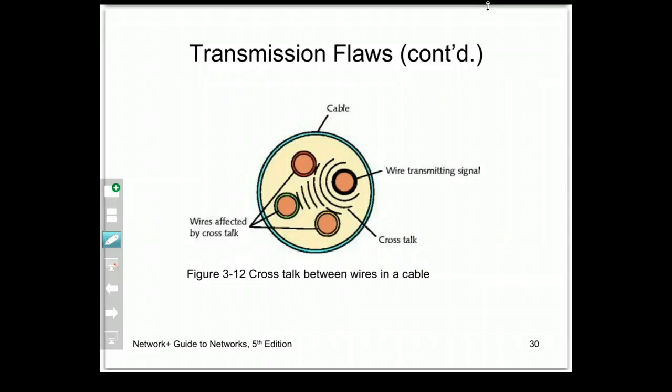These wires in Cat5 cables are twisted, and basically the more twist in the wires, the better. You want the most twisting possible. The more twisting, the less noise susceptible.